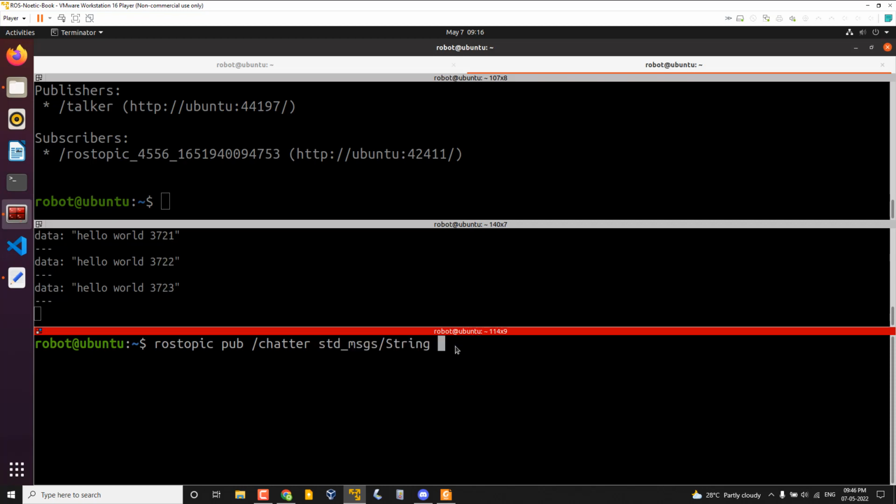I will explain what this std_msgs and string are later. And then the data. I can simply put hello. Then I need to put the rate of publishing, maybe 5 hertz. Now we can try what is happening.